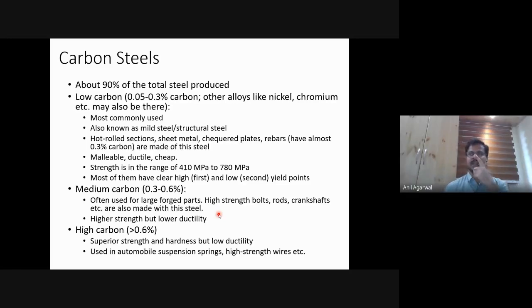So the crankshaft is basically needed because pistons in any engine provide you linear movement, right? Whether it is a diesel engine, a turbine, a gas engine, or the steam engine or whatever. If you have several pistons, all that linear movement has to be converted into a rotational movement, right? Because our wheels require to be rotated at the end, or whatever generator you have has to be rotated. So that linear movement of the piston has to be translated into a rotational movement, and that job is done by a crankshaft.